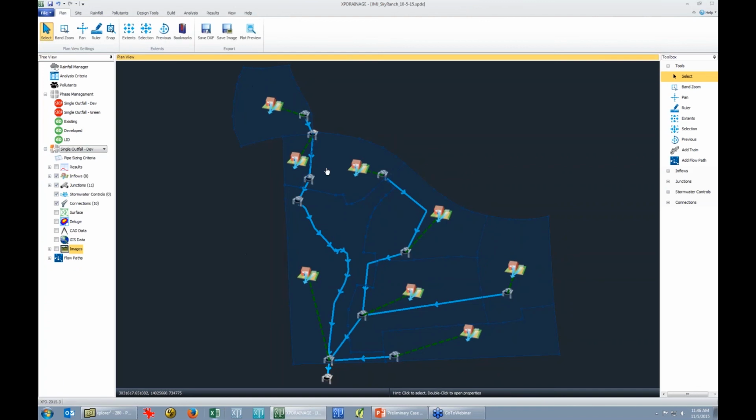All right, so just looking at this plan, let's size all these pipes. That's just one thing we did, and I can show that pretty quickly. So I might add in a flow path. The main trunk line will go from there to there. And we'll see here's that purple main line, and here's all the laterals off of that.